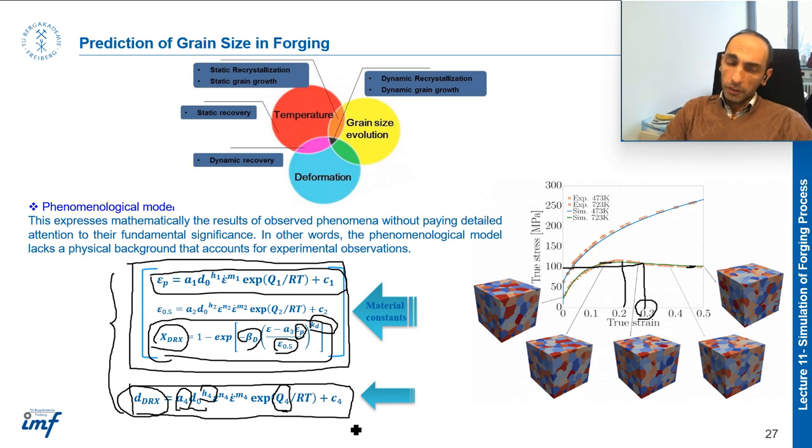Finding these parameters is a different story. There is an approach which is normally used: the Gleeble test. You should perform the hot compression test with the Gleeble at different temperatures and different strain rates, and then when you extract the data, you can obtain these parameters. Of course, you should also measure the grain size on your samples, and then obtain these parameters. It's a time-consuming procedure.